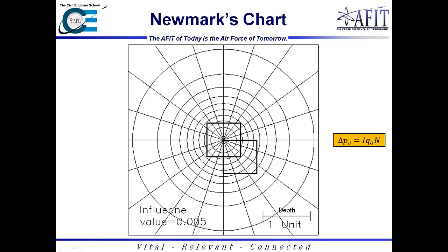And so the way this chart works is you would draw your shape, and you would put the center of the shape or the corner of the shape here in the center, depending on which one you're looking for. So if you're trying to find the stress below the center of the foundation, you would basically put the center right on the center. However, if you're trying to find it at the corner, you would take this corner and put it on the center of the circle there.